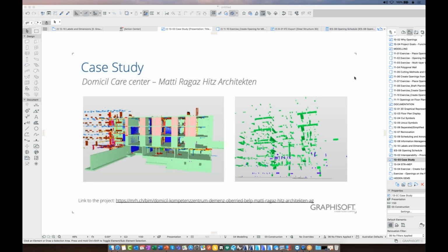Okay, seems to be a pretty new thing here. So the workflow is aimed at coordinating the geometries which are exchanged between architects, structural engineers, and services engineers. And it might be known as provision for or provision of voids. And generally they're placed where services need to be penetrated. Services need to penetrate structural elements or the core of load-bearing structures. So naturally these points will need to be communicated particularly well.